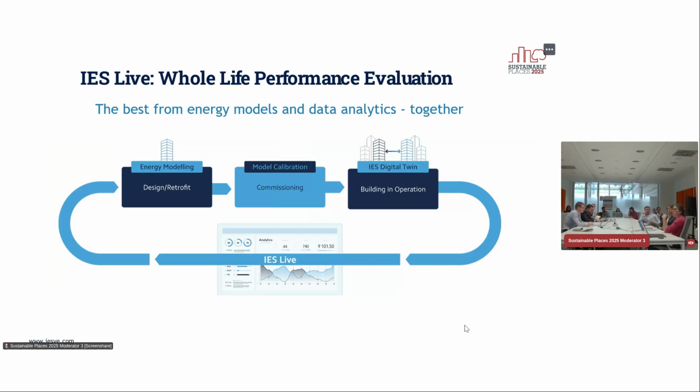So in the end, what it comes down to for us is closing that circle, right? So you have invested into getting an accurate energy model, getting a lot of data, and on the whole life cycle of the building. And so then you start from the design of the retrofit intervention using that model. Then you calibrate it, and it helps also understand the buildings better through the data. Then you couple that live data with the energy model and get to a performance digital twin that can become a long-term life cycle asset to improve the performance, and it's leveraged for future decision making.